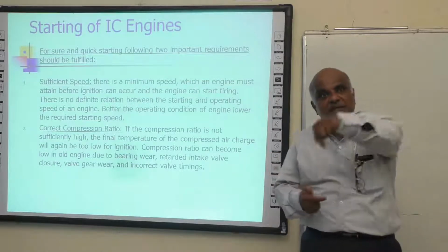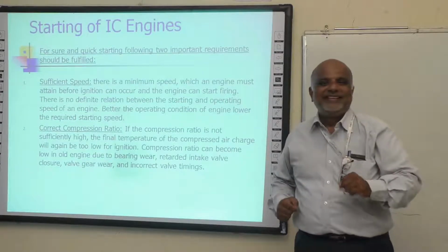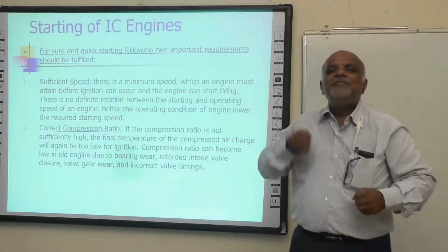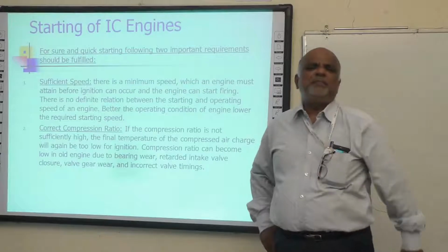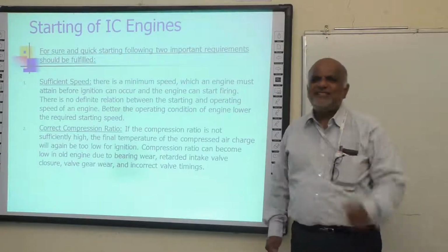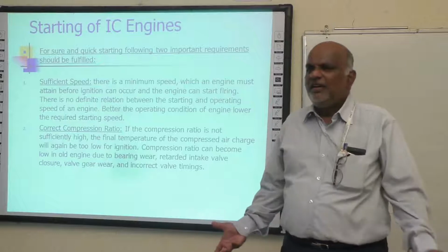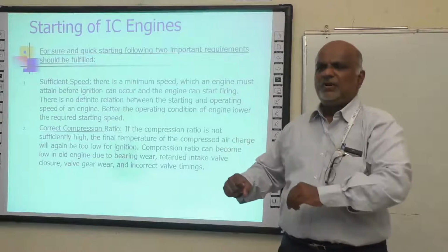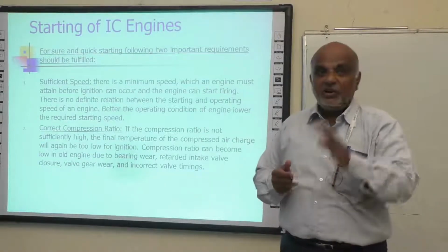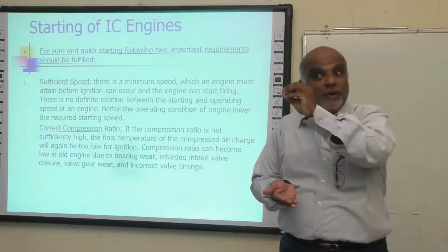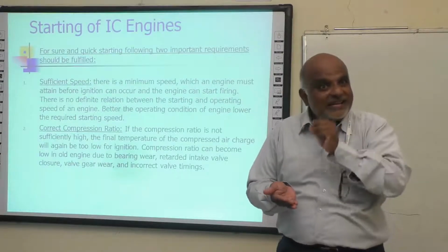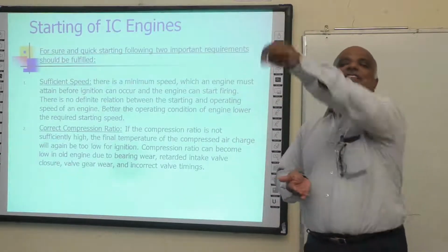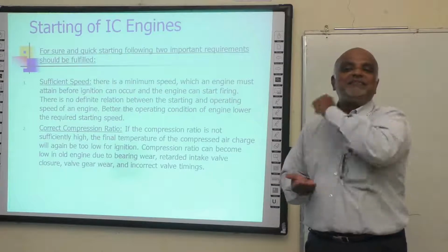Now, what is it that we are making the engine do? Initially, we are giving it an up and down movement. Why is this up and down movement that you have to do? In a standstill engine, can you just give the throttle and put the fuel inside and say start, will it start? No. You have the fuel, but what did I say? The air inside the cylinder must reach the spontaneous ignition temperature of the fuel, and then the fuel you admit inside burns.